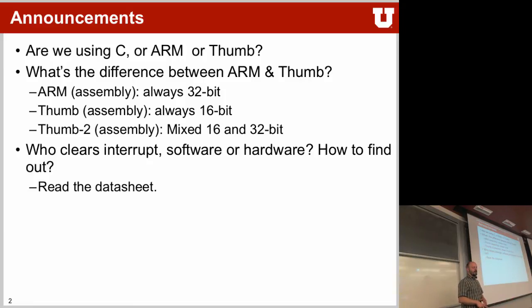Okay. Another question that was very important, I think, is who clears interrupts, software or hardware, and how can I find out? And that's really the problem. You don't really know. It really depends on the peripheral and who implemented that particular peripheral. Oftentimes, you have to clear them in software, but not always. So how can you find out? Well, you read the datasheet.